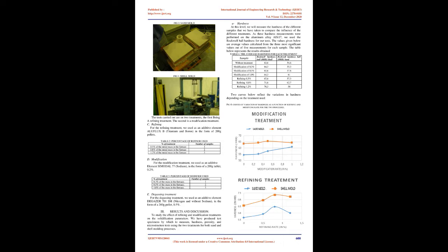2. Experimental procedure. The objective of our study is therefore to be able to control the microstructure, using liquid metal treatment in order to determine the most suitable treatment and casting process for obtaining high performance hypereutectic aluminum silicon parts. For this, we will have to carry out a series of experiments such as tensile tests, hardness tests, and cooling rate measurements. The table below presents the composition of the metal.